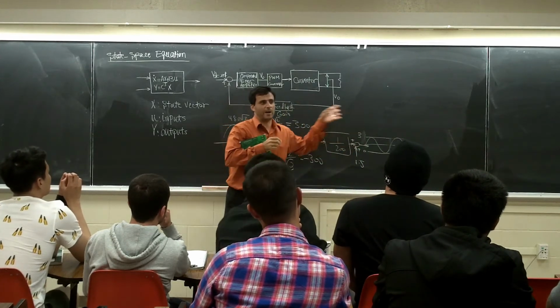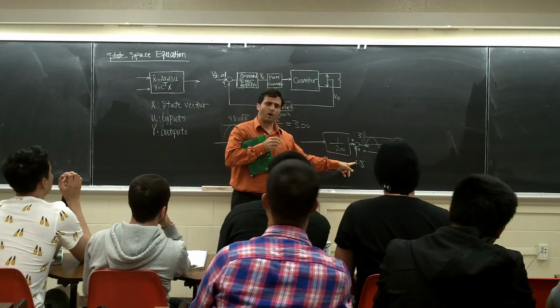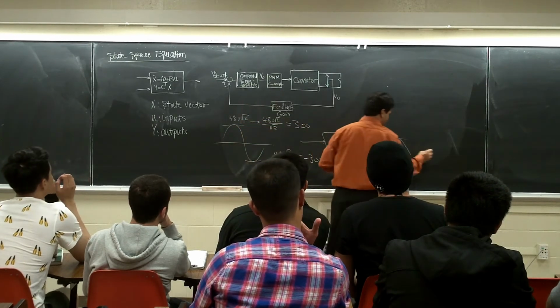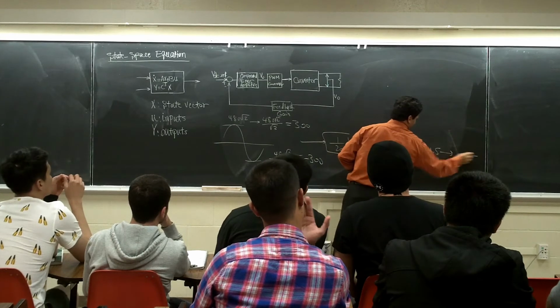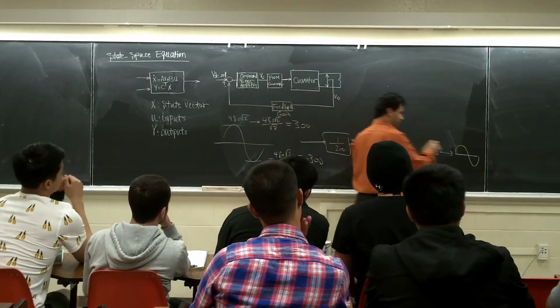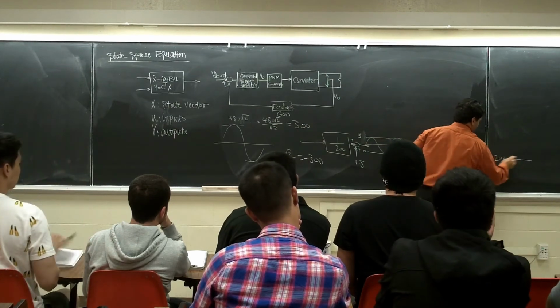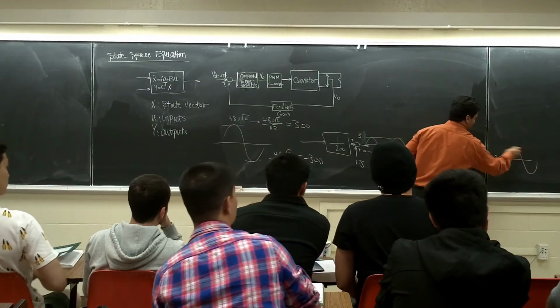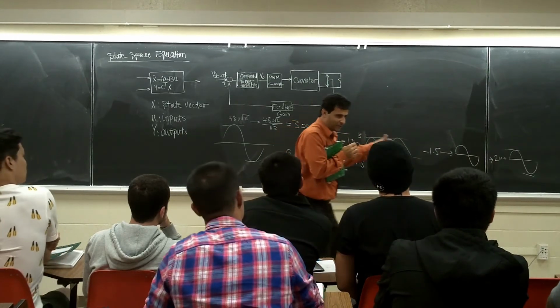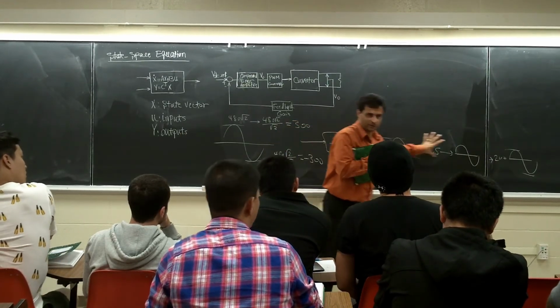So this is your feedback loop, right? 1.5 is the offset. As soon as you get the signal to the DSP, here you subtract 1.5 because I want this one, right? And after that, you multiply it by 200. You build the real signal you have. This is what you do. To bring it into the DSP, you have to do these things, right?